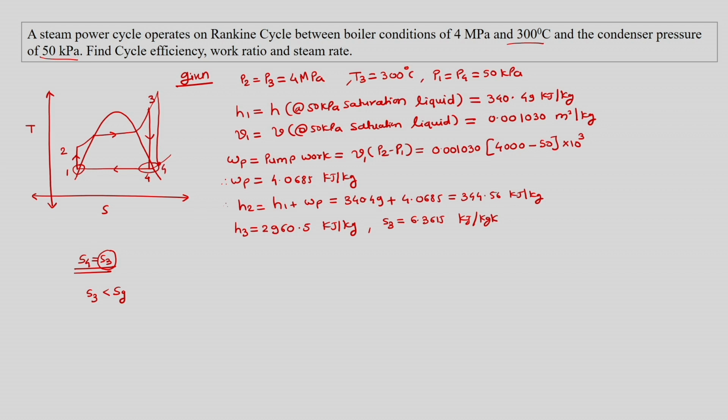In the other case we will have to go to the superheated part corresponding to 50 kilopascal, find out at what temperature the entropy matches with the entropy S3, and when it matches, that temperature at 50 kilopascal is the state 4 condition.